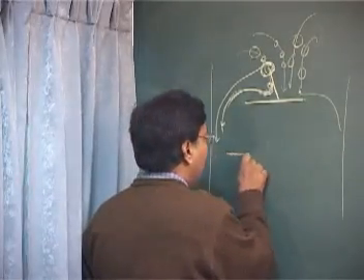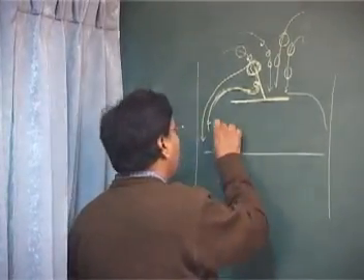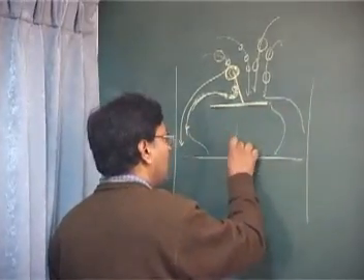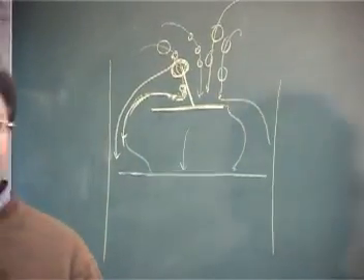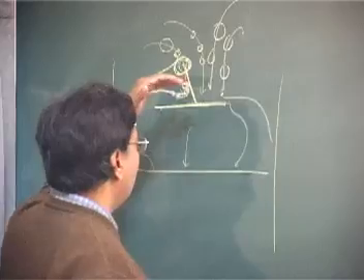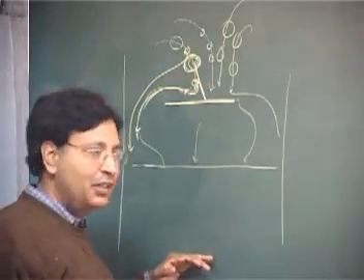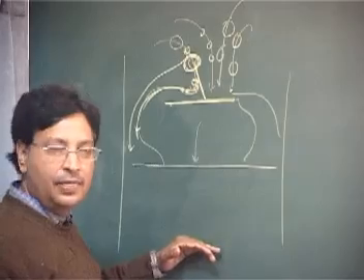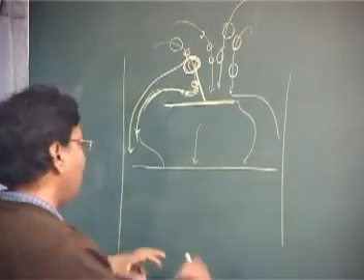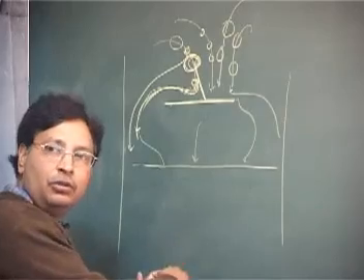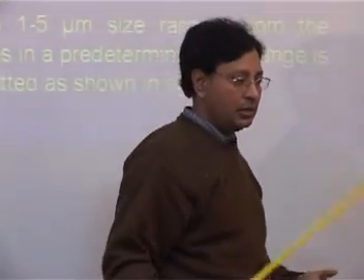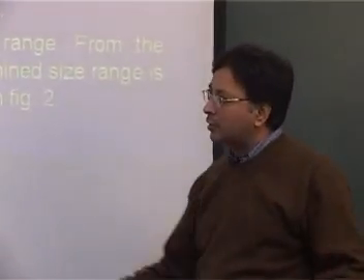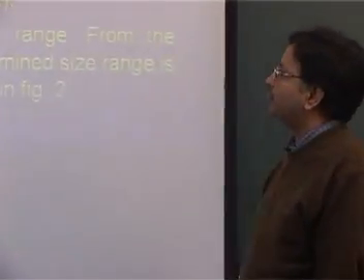And then I can have a filter here, and I'll see all my fine particles collected here. So I can separate them out. This is called a cascade impactor. It's a cascading effect. If I want to fractionalize further, I can add a further plate, so that some particles will stay here, and some will continue to go down. So I can even find the particle size distribution. Sometimes I use the same kind of concept while controlling certain particles, and sometimes for measuring the particles in ambient air.